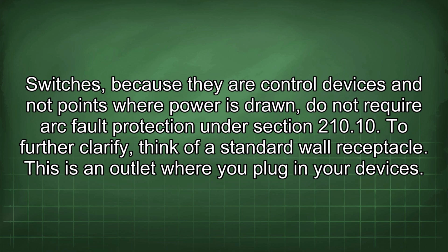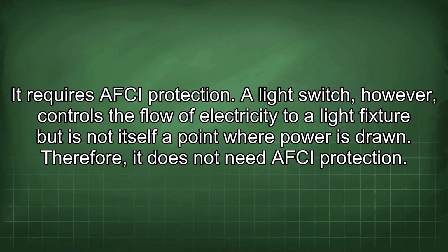To further clarify, think of a standard wall receptacle. This is an outlet where you plug in your devices. It requires AFCI protection. A light switch, however, controls the flow of electricity to a light fixture but is not itself a point where power is drawn. Therefore, it does not need AFCI protection.